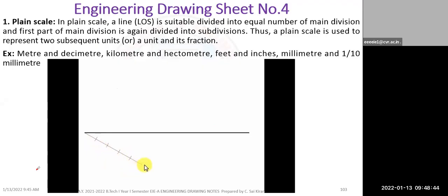Now, the next step is extremely important, guys. You need to make use of a mini drafter. You can keep your mini drafter over here. And then with this point and this point, you need to join these 2 points. That's it. Then tighten the screw, then take your drafter ahead over here, that is at the fourth arc, and again draw a line. You can clearly see that these 2 lines are absolutely parallel to each other. If you keep on moving your drafter to this point, this point, this point, you'll ultimately realize that all the lines drawn are absolutely parallel to each other. And eventually, this dark line that I've made gets divided into 5 equal parts.